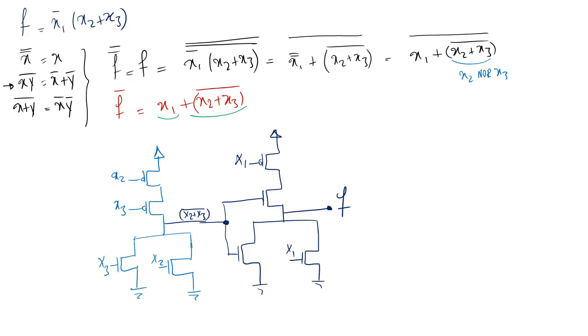So with this design, I'm going to have 8 transistors. And the more important thing is that it's only 2 layers. I don't need to invert anything at the input or output. So we went from a 14 transistor, 4-layer design all the way to an 8 transistor, 2-layer design, almost 50% saving in terms of transistors and in terms of the speed of our design.